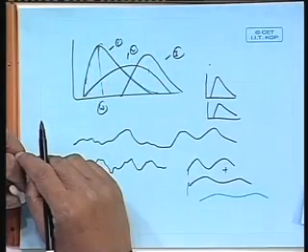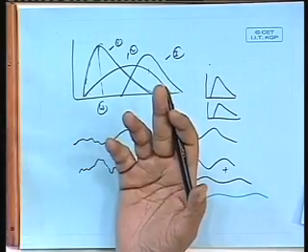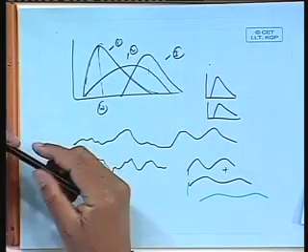Now conversely, in the same location, for the same wind speed, at the same time of the year, with all other conditions being the same, you would expect that although the signals are different, if you have synthesized them and plotted this graph, it will be the same frequency distribution. That is very logical to assume, and this is exactly why the spectrum concept is even more appealing, because it tells me the frequency distribution of the heights or amplitudes, and that distribution is more or less constant for a location and for a given wind speed, for various excitations.